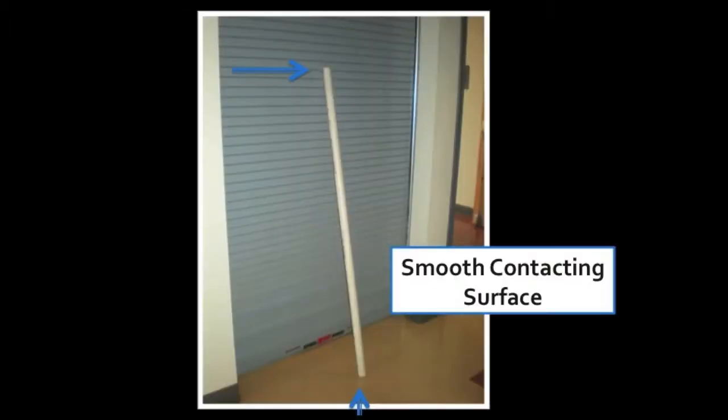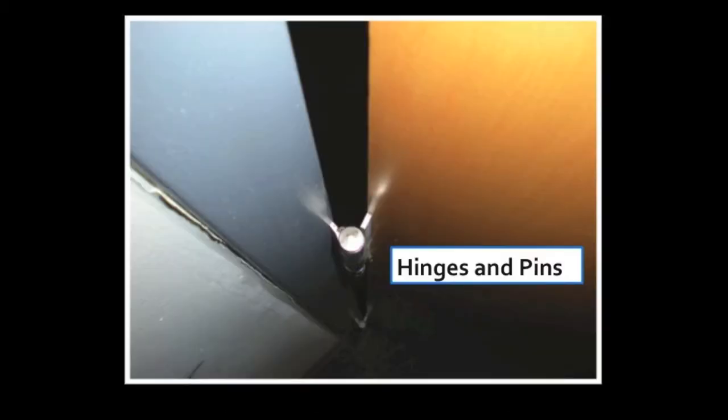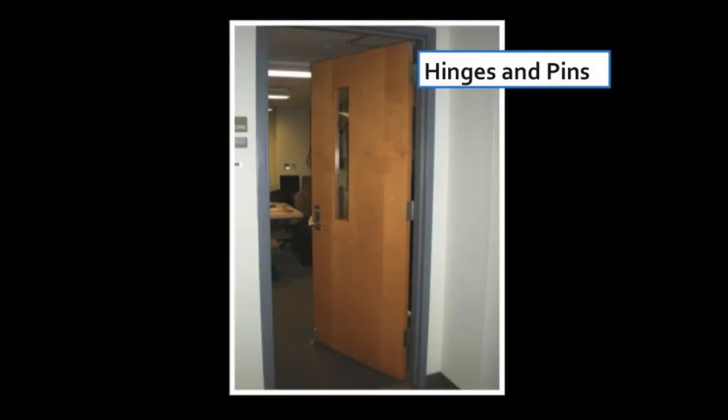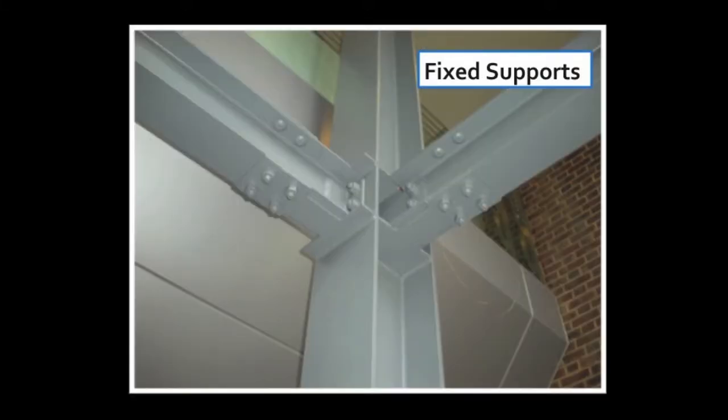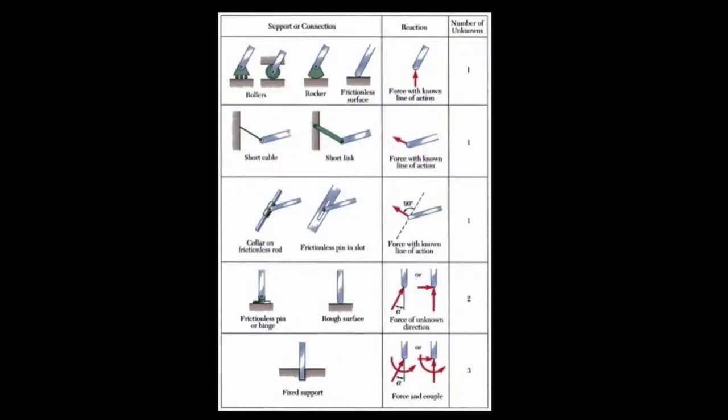We also have smooth contacting surfaces. Smooth contacting surfaces act in one direction, perpendicular to the surface of contact. Another type of support reactions includes pins and hinges. These supports prevent horizontal and vertical translation, but not rotation. For example, when a force acts on this door, the door rotates about an axis through the hinges. Fixed reactions prevent horizontal and vertical translation and rotation. There are many other types of support reactions also.